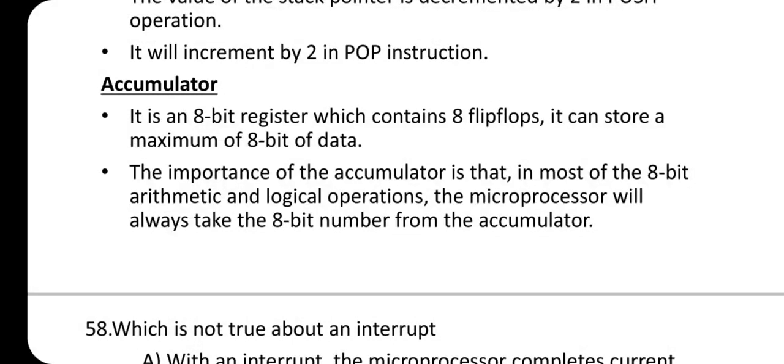Accumulator. It is an 8-bit register which contains 8 flip-flops. It can store a maximum of 8 bits of data. The importance of the accumulator is that in most of the 8-bit arithmetic and logical operations, the microprocessor will always take the 8-bit number from the accumulator.